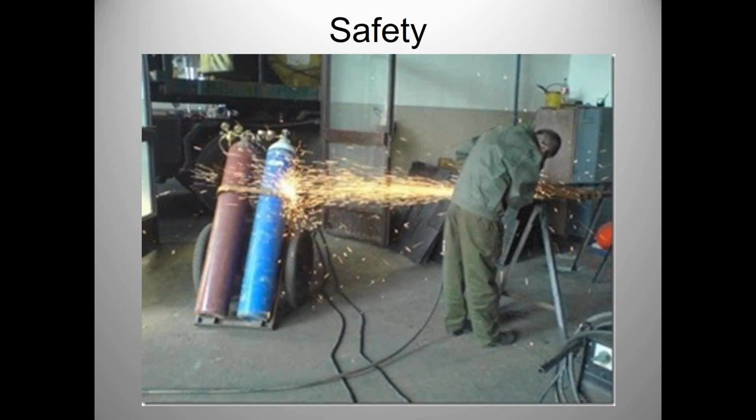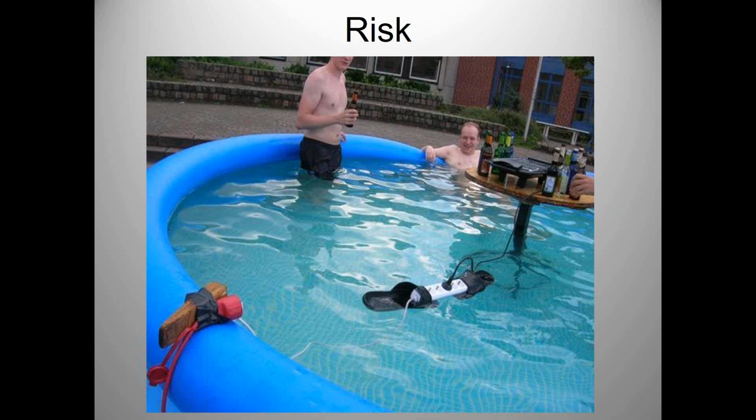And sometimes we have to look at the safety systems in our shop. What's the potential here, if something happened with this guy grinding and throwing sparks right onto his acetylene and oxygen tanks? It's probably one in a million that there might be a leak up top and something catches on fire. But I've actually seen this in practice, not only at the facility I came from in the past. Just a spark like this gets the top of the bottle burning, or maybe the hose is burning. I've heard of serious accidents where these tanks have caught on fire, dropped over and broken the valve off, and the tank goes shooting across the floor like a torpedo. I saw some pictures where one went through a block wall in a shop. So again, potential for a safety incident.